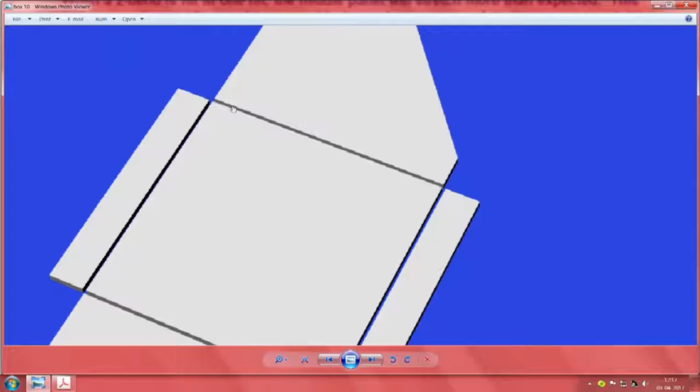This width cannot be this much, it needs to be a little smaller or it needs to be bigger. In case it is overlapping this, it needs to be two thicknesses wide compared to this. In case it is coming inside, you need to have probably two thicknesses smaller. Otherwise, we end up with a corner which is not filled, and I can see edges of both the sheets in the corner.